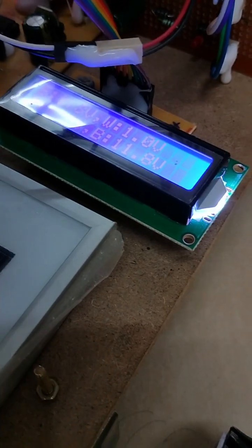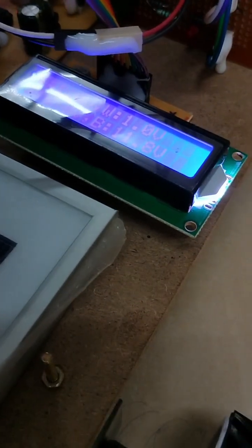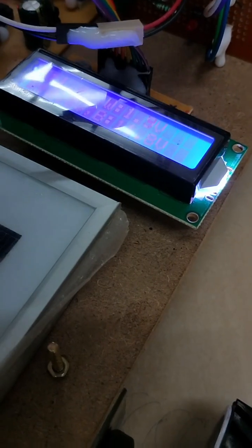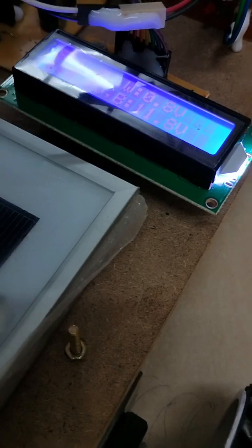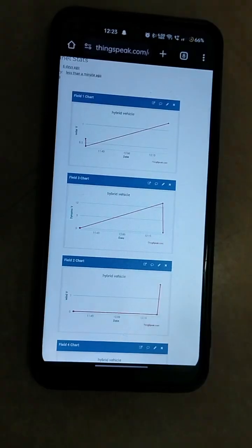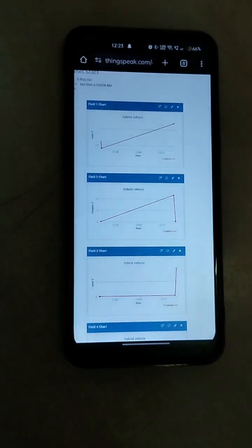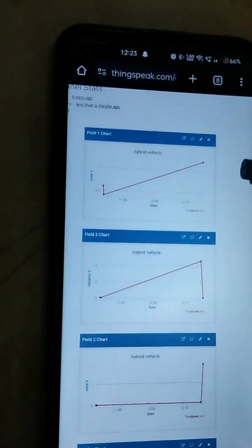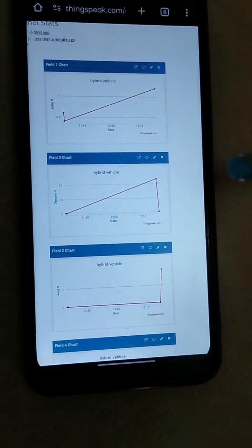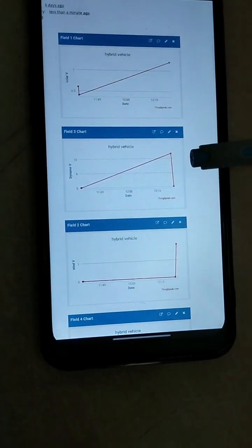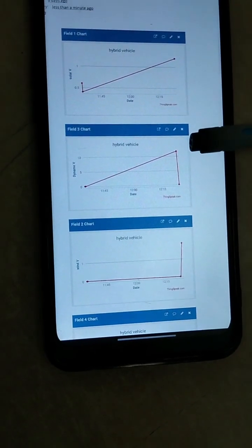We can see the wind varying from 0.8, 1.9, 1.1, 1.5 and 1.9. Also we can observe the battery at 11.8 volts, and in the graphs, this is the solar, where the light is a lot, so we can see the increase in solar. In the dynamos, due to no rotation of the vehicle, we can observe a sudden fall of the dynamos.